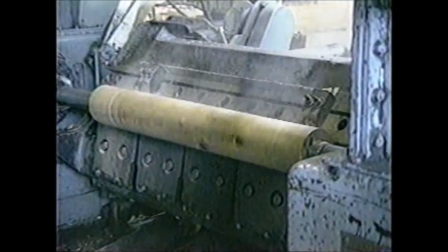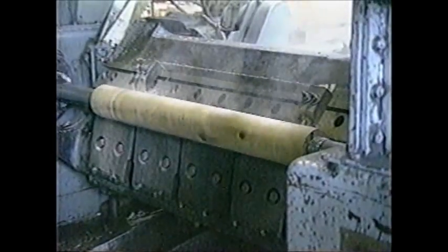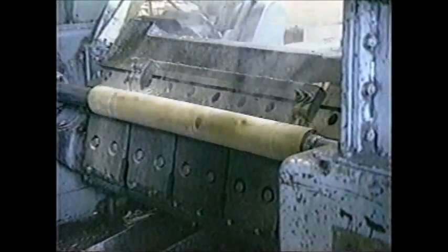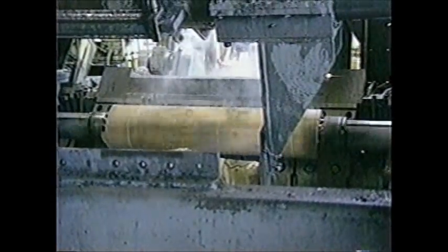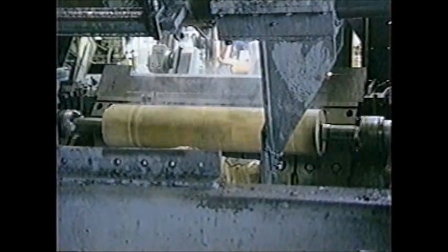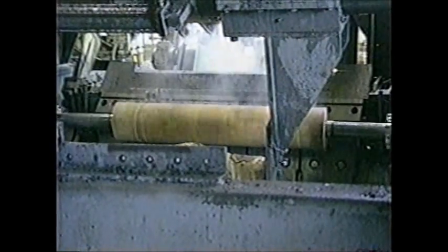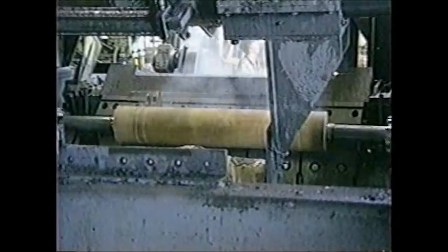Hardwoods, such as hard maple and beech, are considerably harder to peel than softwoods and require a slower rate of feed. 2-stage chucks are commonly used, with the larger outer diameter retracting after the log diameter is reduced, to allow the peeling of the log to a smaller core diameter.